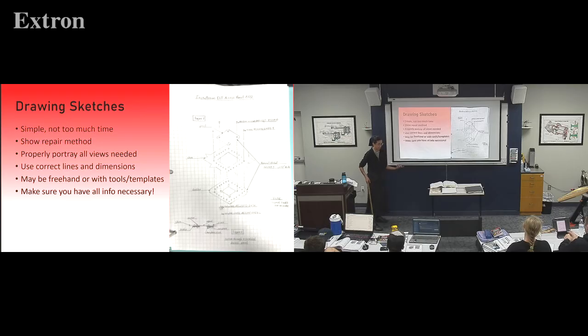If you need a center line, use that. If there are hidden lines, use hidden lines properly. And then you do need to have dimensions where appropriate. If you have a super steady hand, which I do not, you can do it freehand. Are those jagged lines? Yes, correct. I did use decent break lines because that's representing the whole fuselage there.